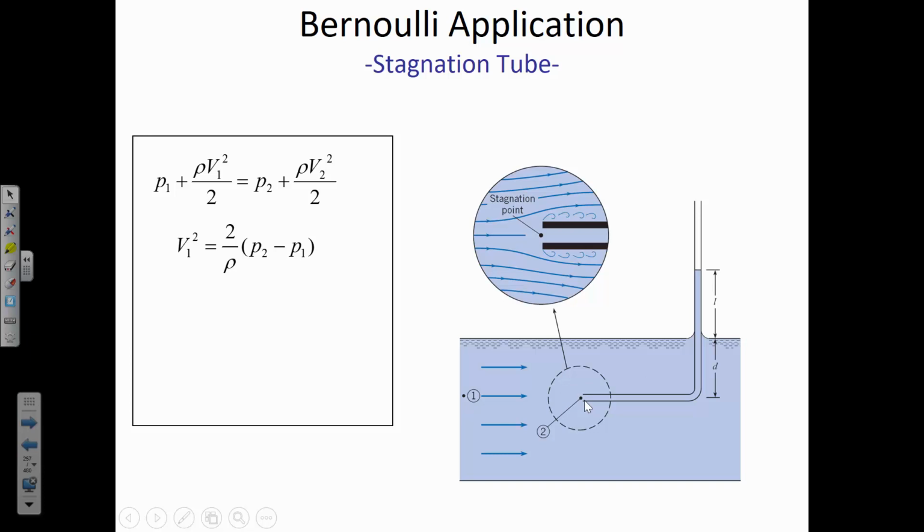Additional pressure in the amount of the velocity that was lost. That direct exchange of energy from velocity head to pressure head. So if we approximate the pressure at location 1 as the depth, here D, from the surface down to this horizontal plane multiplied by gamma. In other words, we're just using the hydrostatic equation to find out what the pressure at 1 is.